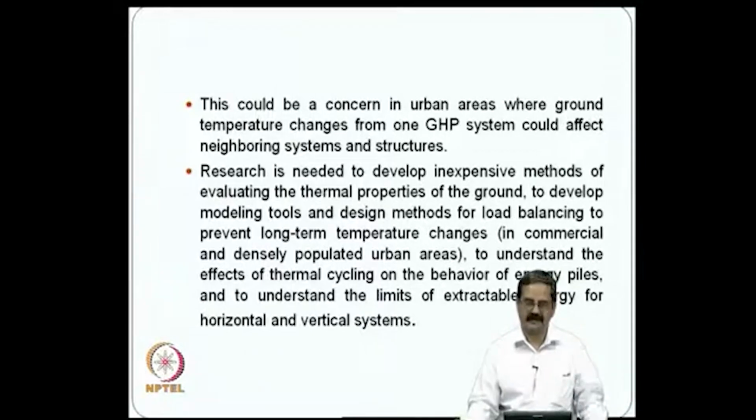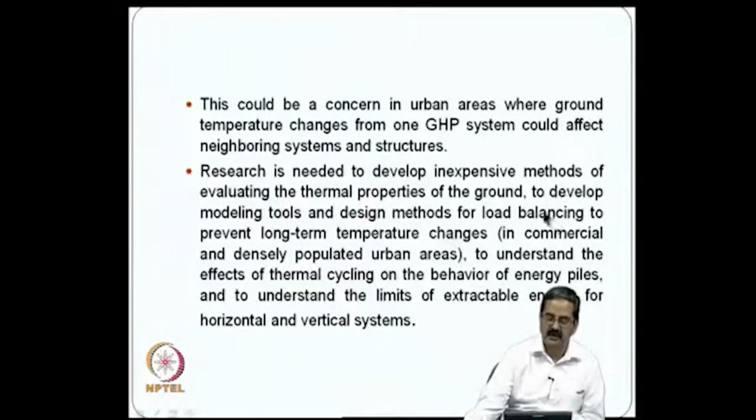So there is a lot of balancing that needs to be done, and research is required to develop inexpensive methods of evaluating the thermal properties of the ground. In fact, we do not have very good in situ methods. We should go for in situ methods of measuring heat conductivity of the soil, and also develop modeling tools and design methods for load balancing to prevent long-term temperature changes.